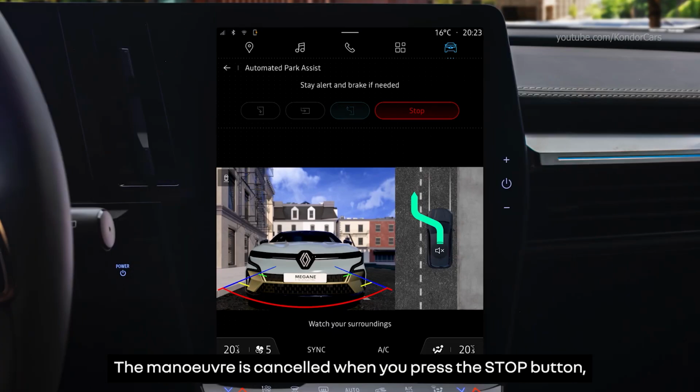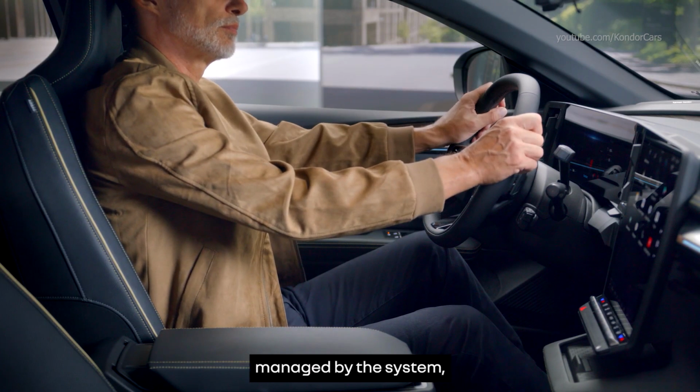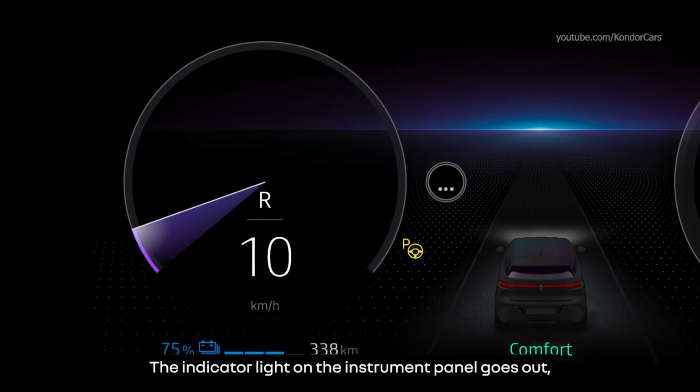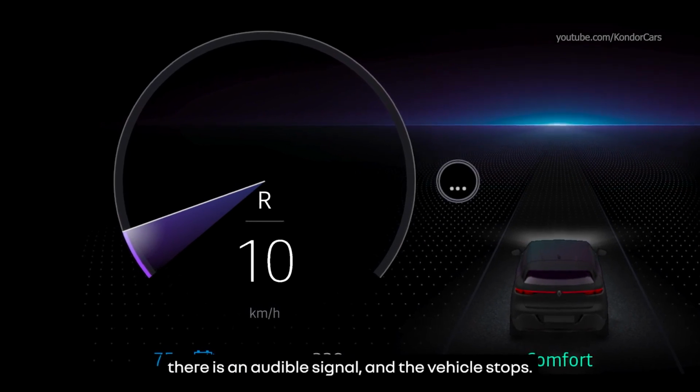The maneuver is cancelled when you press the stop button, when you operate any of the vehicle controls managed by the system, or when the vehicle has performed more than 10 forward and reverse maneuvers. The indicator light on the instrument panel goes out, there is an audible signal, and the vehicle stops.